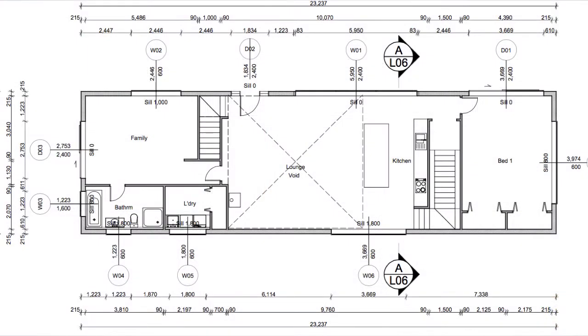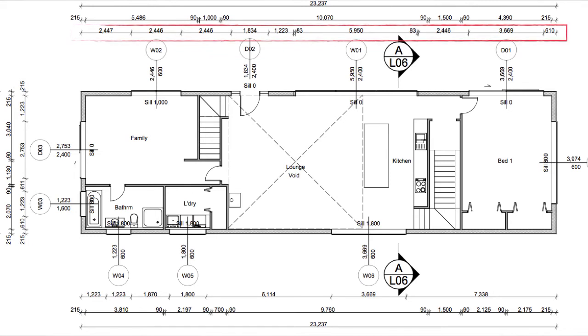The best way to do it is this, looking at this example, actually showing an extra line of dimensions for all the openings that are showing clear opening dimensions, and also information about each window, not just the size but also the sill height. And let's just make sure that we actually talk about clear opening required, because that's how the panels are actually going to arrive on site.